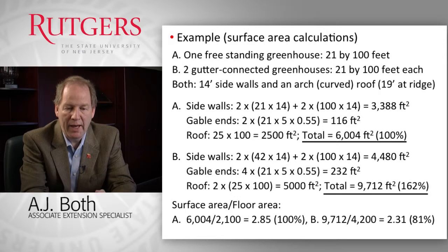So once you've done all that, you can calculate the overall heat loss for your structure. And again, you need to take into consideration the fuel conversion efficiency to be able to eventually come up with your boiler capacity.